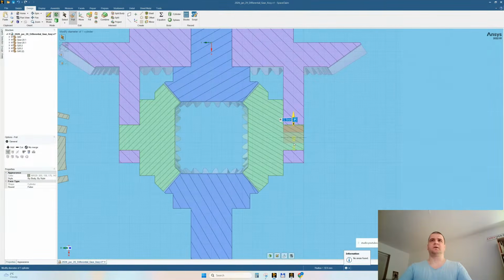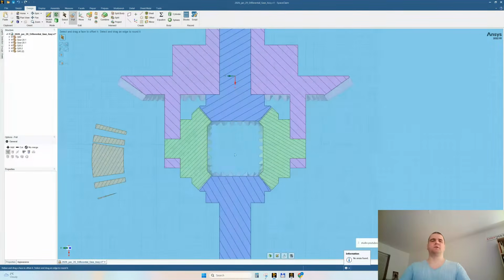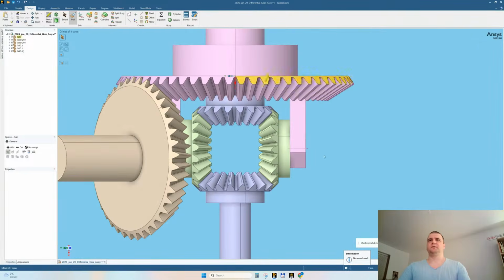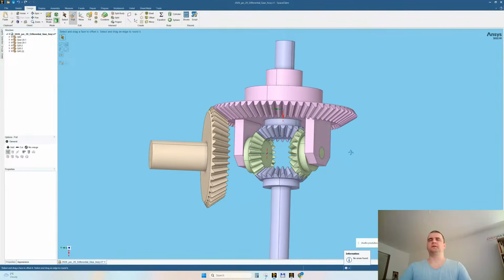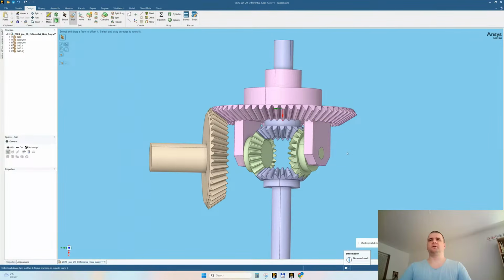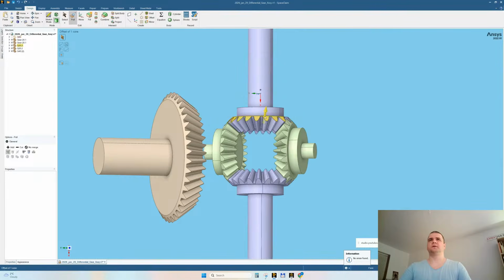We can also choose not to create the Revolute joints, because being in explicit dynamics, we have an overall body interaction, a frictionless body interaction overall. So this is nice. We might need to maybe correct it, or maybe let's correct it now. What will we do? Will we make the shafts' diameters smaller or the holes bigger? Let's make the shafts thinner. So this, let's make it 19.9.